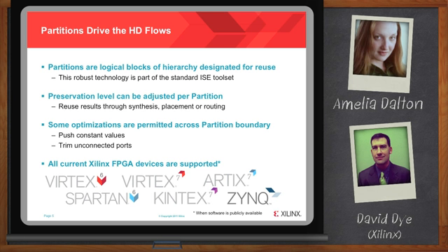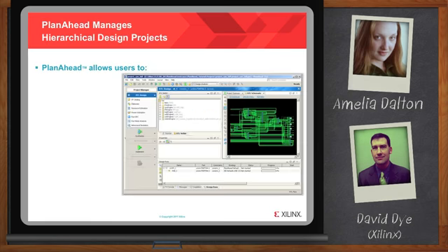Okay, so David, are partitions easy to use? And how does one manage these hierarchical flows? Well, we certainly think they're very easy to use. All these flows can be run on the command line or via scripts. But a great way to use these tools is within PlanAhead, our front-to-back design flow and project management environment. PlanAhead gives you graphical control over all aspects of the hierarchical design flows, as well as an interface to the Tcl engines.